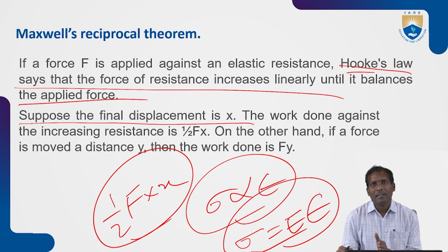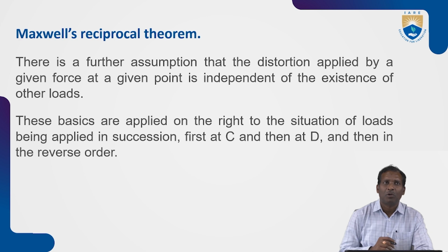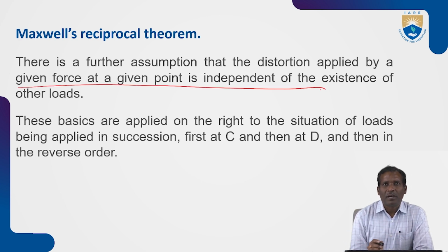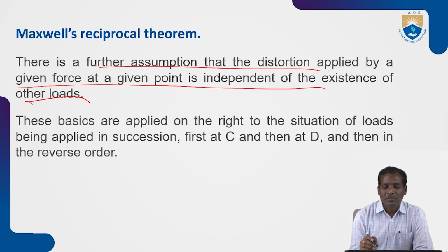On the other hand, if a force is moved a distance y, then the work done is F times y. So there is a further assumption that the distortion applied by a given force at a given point is independent of the existence of the other loads.